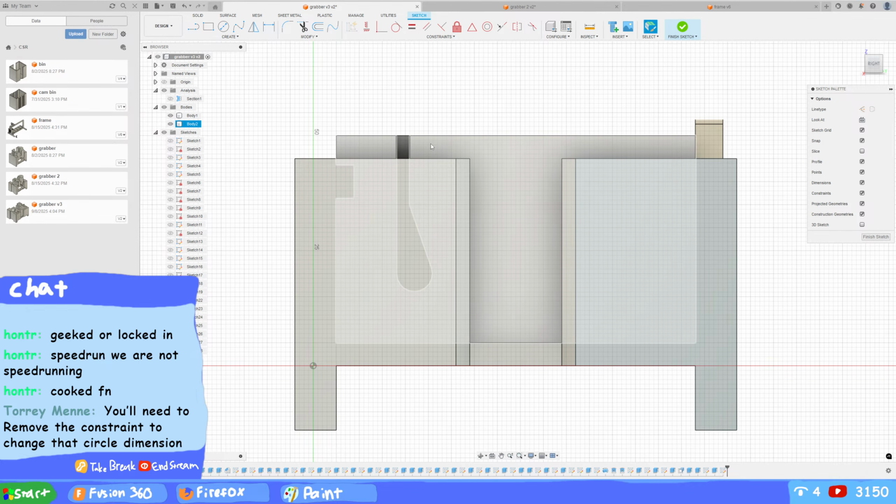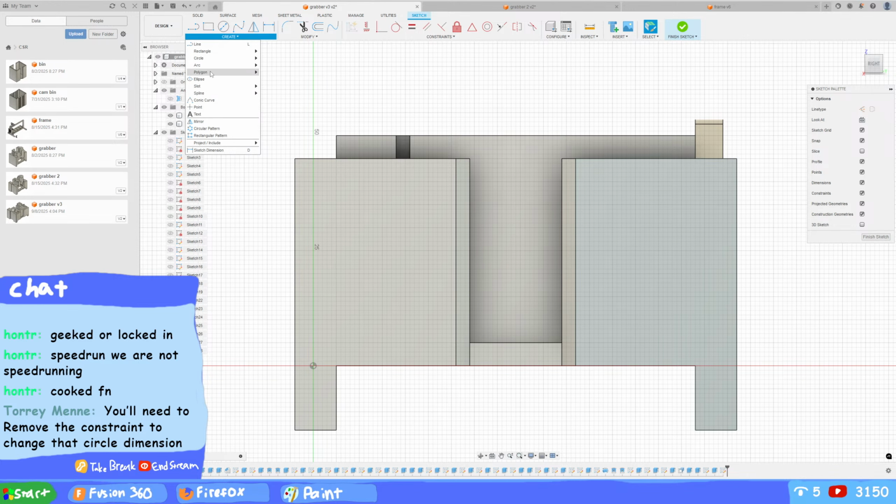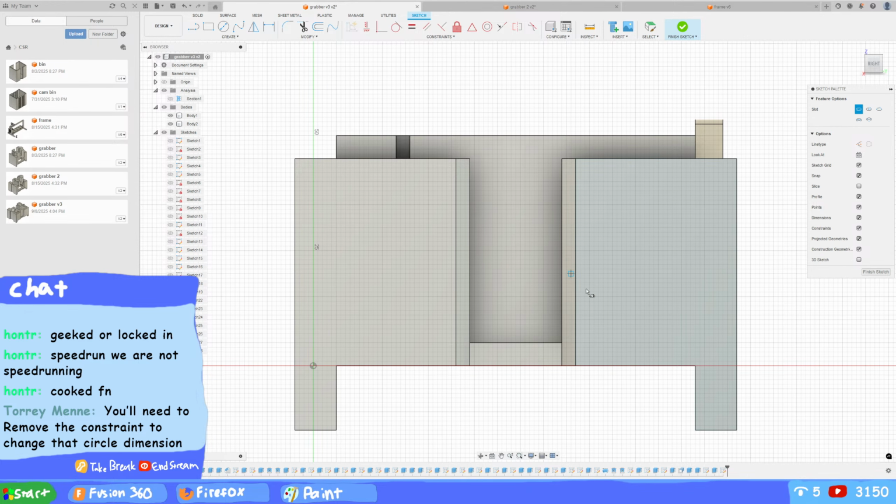And then I need to figure out how far it needs to be able to go. I don't know that. I guess like 3 millimeters? No, 3 centimeters? I have no idea. But basically, create slot. Center to center is good. We will start 5 millimeters off. That's probably a good number. And then, you know what? We can do 30 millimeters. I think 30 is about right.